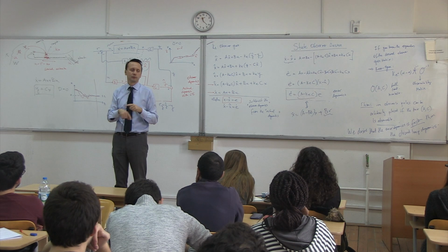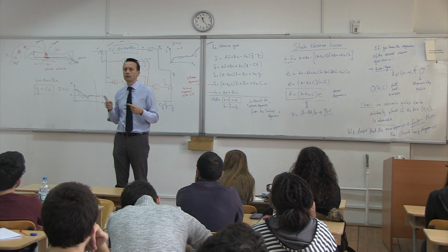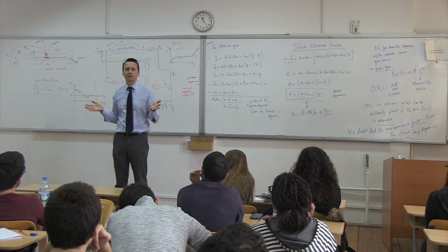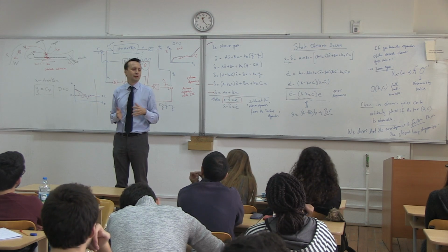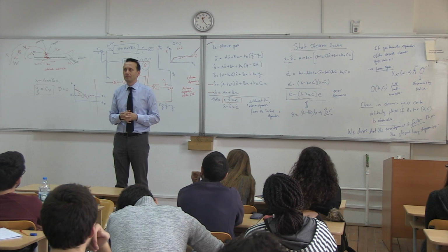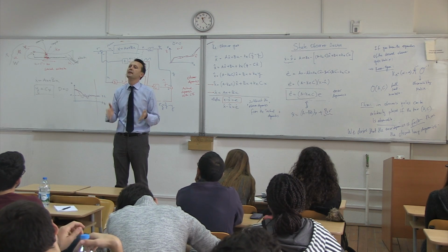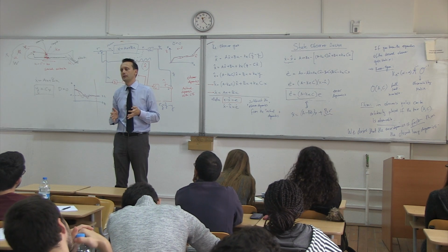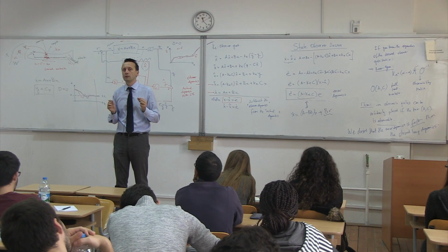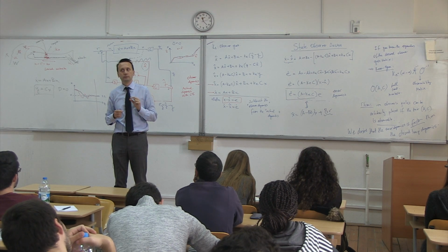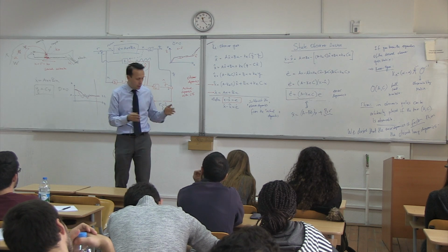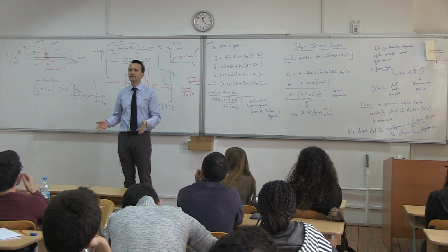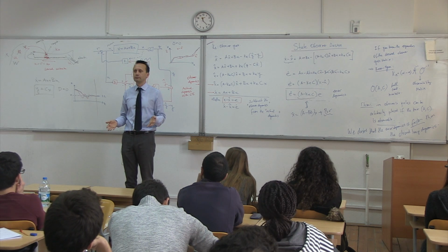You go to the wind tunnel, you do the aerodynamic derivatives, and how good are these tests anyway in the wind tunnel? Are they perfect? No. So you will never find the exact ABC matrix. There will always be some errors. Sometimes the errors are small, but they can be very large as well. And you think you have the ABC matrix of your airplane, but in fact you don't.